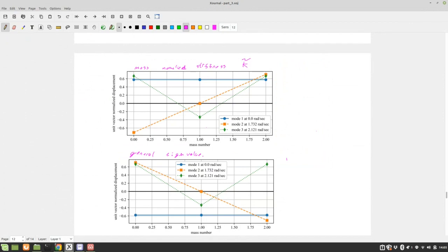Okay. So there's definitely a difference in the first mode, right? This first mode is negative, that first mode is positive. Generally a difference in the second mode, right? This one's down, that one's up, this plane turns to the left, that one turns to the right. Depends which way you look at it, I guess. But are they the same information? Information-wise, they're identical, because there's no information in the mode shape other than the shape.